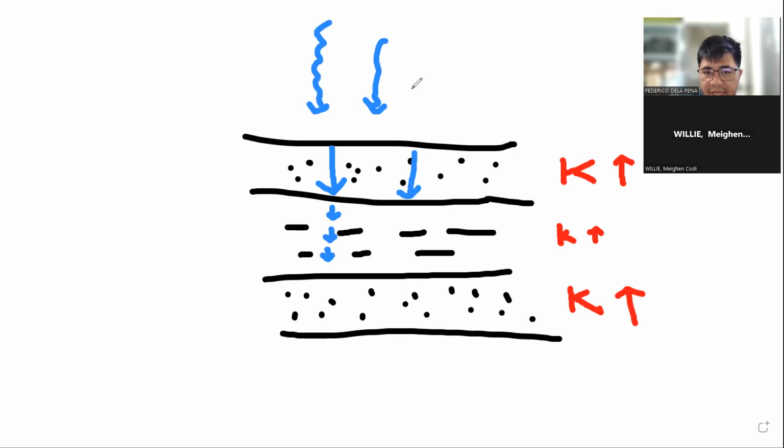And note that the flow of water has no other option but to traverse the silt layer, okay, if it's going perpendicular to the bedding. Okay. So all of them will have to pass through this silt layer first before it can travel through the third sandstone layer. Okay.